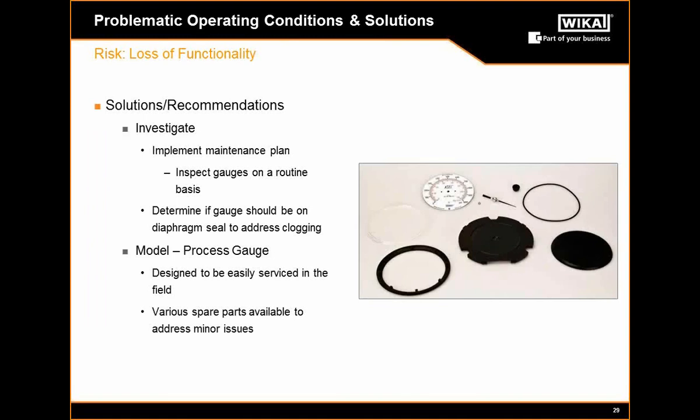The best way to address these is a standard gauge maintenance plan, and to support a gauge maintenance procedure, we can offer individual parts. Let's say, for example, just a window has been broken. If you leave that window broken out in the field, the ingress of contaminants will eventually break that gauge down to the point where it doesn't operate. But by simply replacing the window, now you've got a completely functional gauge with the hermetical seal that will keep it operating long into the future.